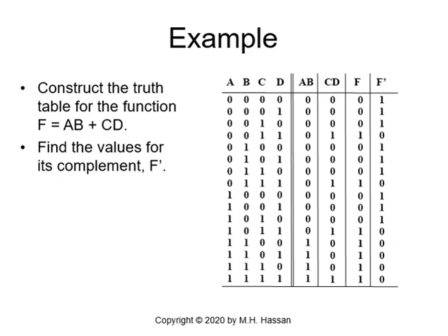And as an example, we would like to construct the truth table for the function AB or CD. Again, here we will calculate the term AB, we'll calculate CD. This is a 4-variable function. As you can see, the truth table will be 0, 1, 0, 1, 0, 1 for D. Then 0, 0, 1, 1, 0, 0, 1, 1 for C. So 4 zeros and 4 ones, 4 zeros and 4 ones, then 8 zeros and 8 ones to fill out the full combinations. We will add A and B.